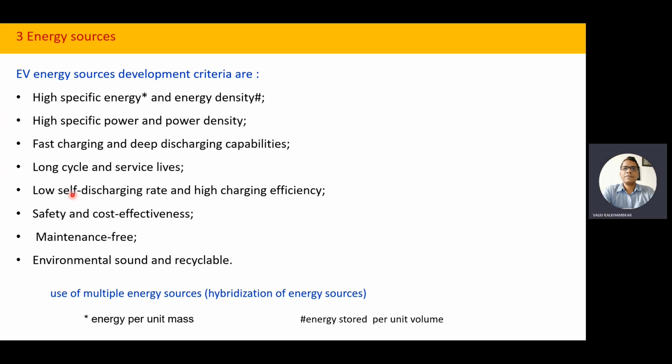Now, once we discharge the battery, it is supplying power or energy to the load. Self-discharge is whenever the battery is not used, not connected to any load, just idle. Then also some energy loss is there, some small discharge called self-discharge in the idle condition. This discharge is because of the inherent chemical reactions, the chemical property of the battery.